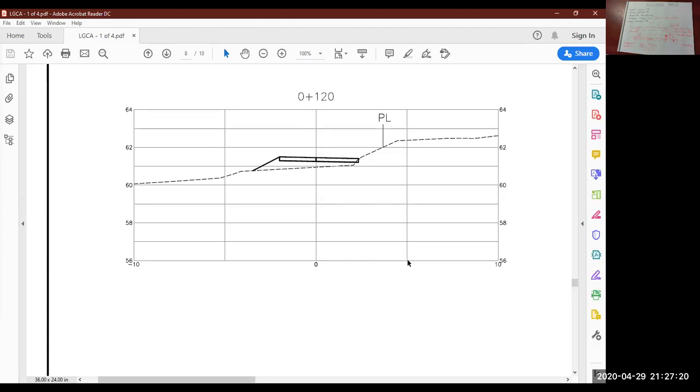What that also tells you is from 0 to this line is 5 meters. For vertical scale, again, you're given elevations here. Here's 58, there's 60. Of course, the one in the middle is 59. So the distance between this line to the next line is 1 meter.